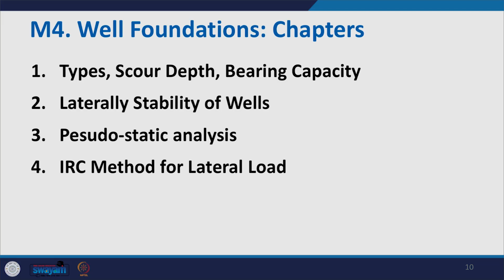The fourth module of this course will be on well foundations, where the first chapter will talk about types, scour depth, and bearing capacity. Then we will discuss the lateral stability of wells, pseudostatic analysis, and Indian Roads Congress methods for lateral loads for well foundations.